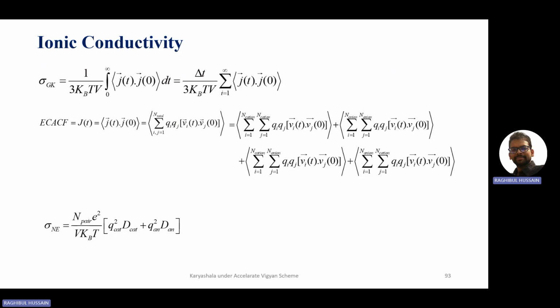You have to compute this from the velocity file. Although, as I said, in the integrator scheme like velocity Verlet or leapfrog you can get the velocity, you will miss the sophistication of computational programs like NAMD, GROMACS, and LAMMPS. Therefore, it's better to extract the force file, the velocity file, as well as the trajectory files to get this data.